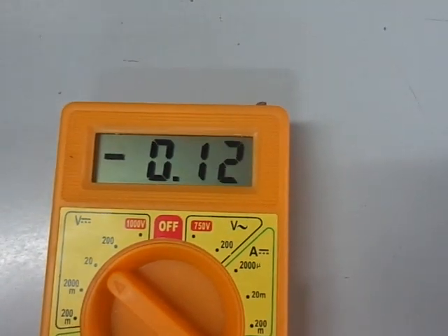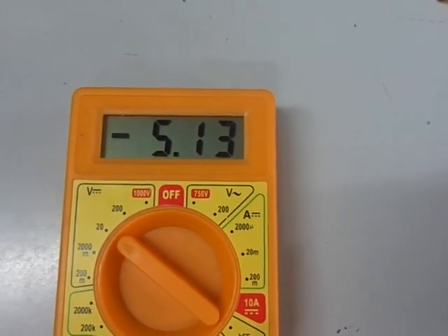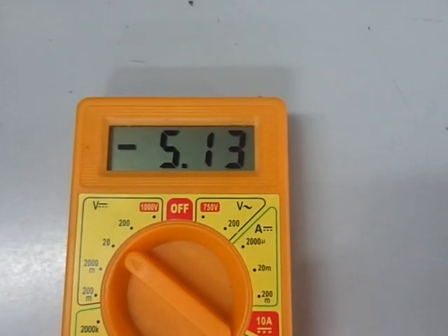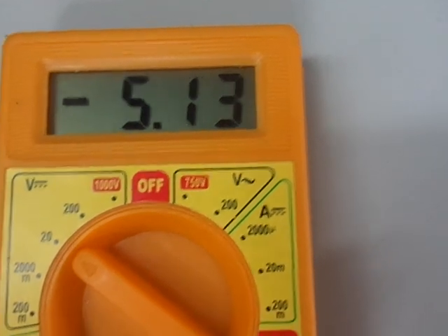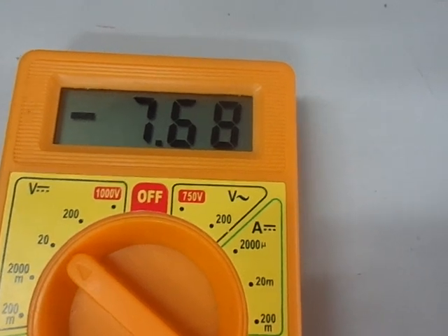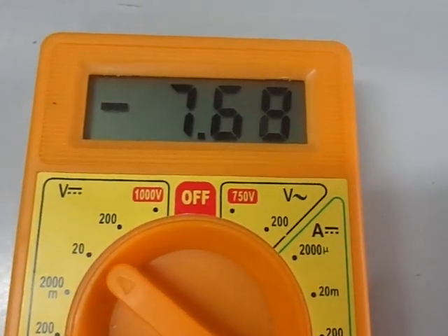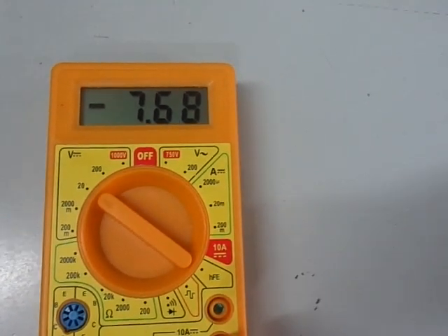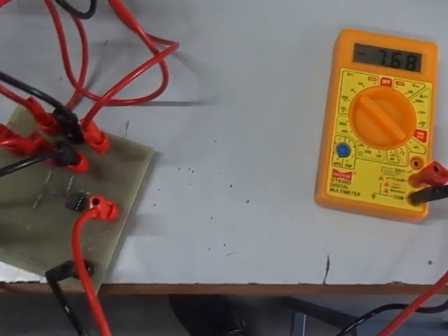Now if we take A1 equal to 1 and A0 equal to 0, theoretically we are expecting the output voltage to be minus 5 volt, and practically we are getting minus 5.13 volts, means again for this case also the analog output voltage corresponding to the digital input signal is obtained as per the theoretical values. Now I am connecting A0 as well as A1, both to logic 1, and theoretically we are expecting the output voltage to be minus 7.5 volts, and practically we are getting minus 7.68 volt, means theoretical and practical values are mostly matching with each other. Hence the conversion of digital signal to analog signal is obtained in this case.